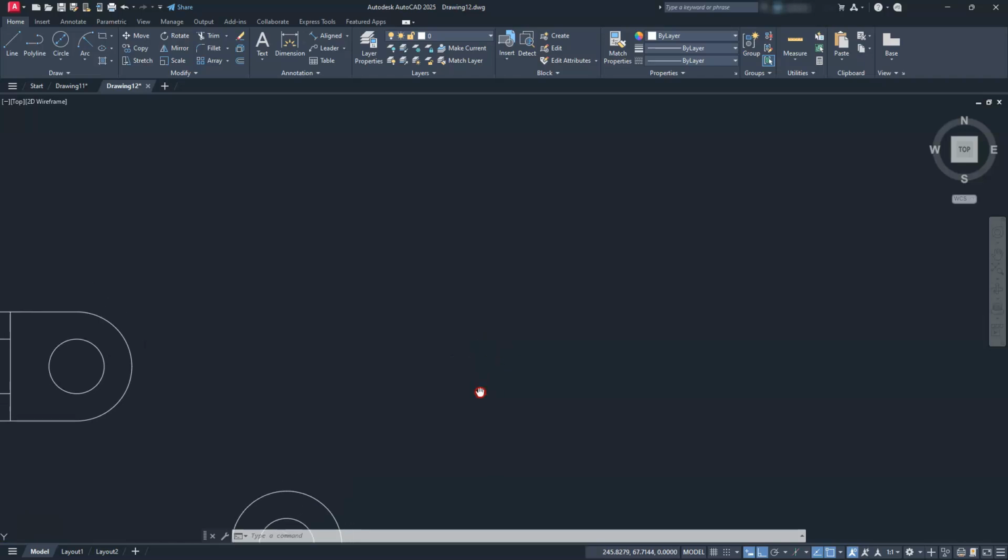Let's go ahead and create this isometric. First thing we need to do is go ahead and put our isometric on. Let's make sure our ortho is on. I'm going to switch to isometric left. And then I'll create that first shape that I told you I was going to create. So I'm going to go with a line. Click here, go down 50.